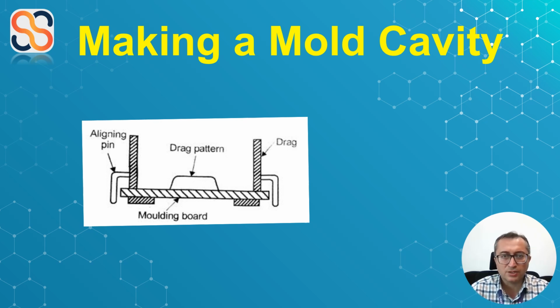Next, we place the drag portion of the pattern with the parting surface facing down on the bottom board. After that, we sprinkle facing sand carefully all around the pattern. This helps ensure that the pattern will not stick to the molding sand when we pull it out later.